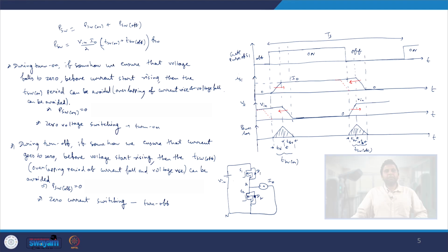Now, since we have voltage source converters driven by the voltage source and having a kind of constant current at the terminal, because most of the time at the output terminals of the half bridge you are connecting a huge inductor followed by load or source, you are actually drawing a constant current from the output of the half bridge.